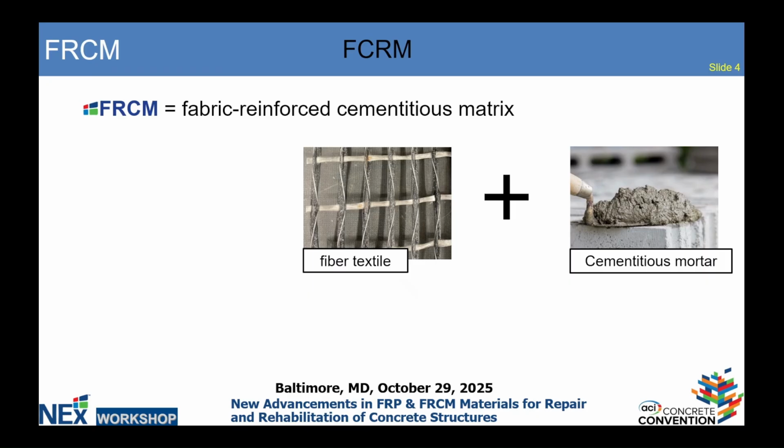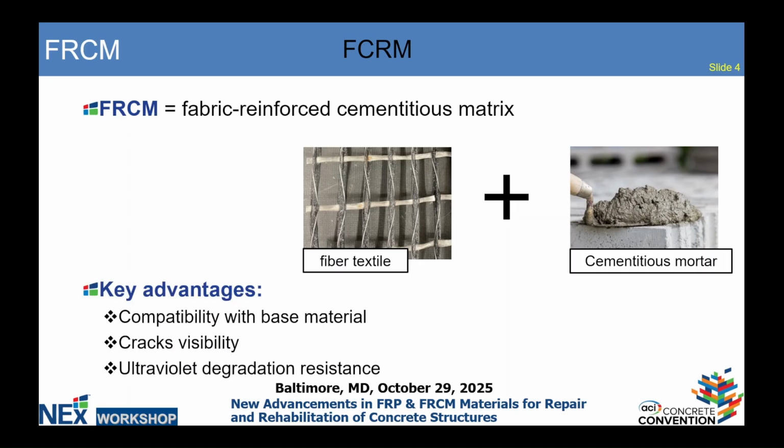Now, I wanted to explain what FRCM is, but apparently it was made clear in the previous presentations. I will just touch on the key advantages of this system. It is compatible with the base material, especially when talking about concrete. Because of this compatibility, cracks are visible on the concrete surface, unlike other retrofitting or strengthening systems. Also, ultraviolet degradation resistance is another key advantage.